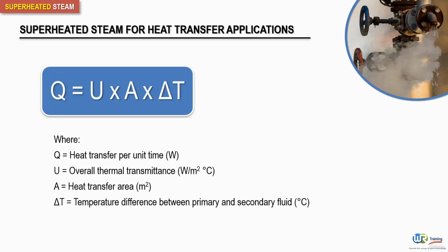Predicting the size of heat transfer surfaces using superheated steam is difficult and complex. In practice, the basic data needed to perform such calculations is either unknown or empirically obtained, putting their reliability and accuracy in doubt. Clearly, as superheated steam is less effective at transferring heat than saturated steam, then any heating area using superheated steam would have to be larger than a saturated steam coil operating at the same pressure to deliver the same heat flow rate.